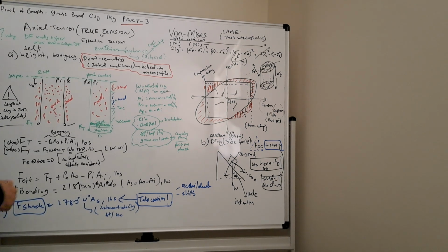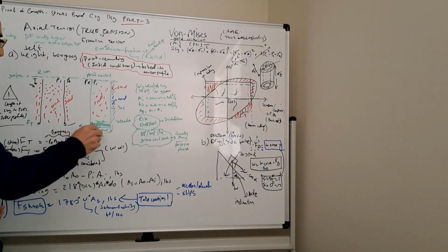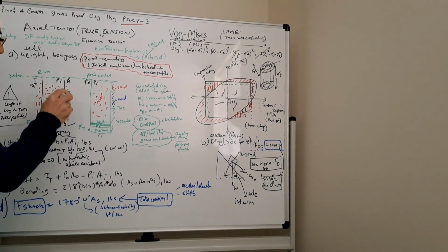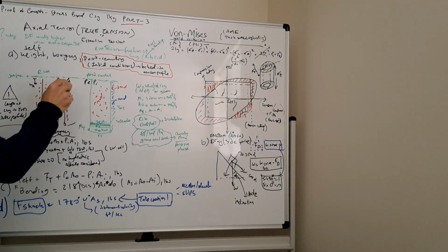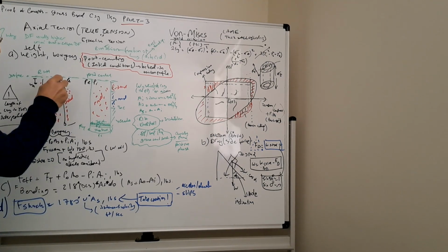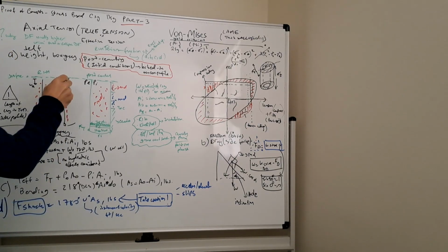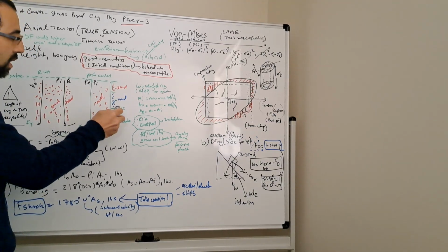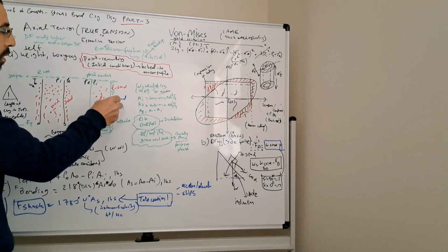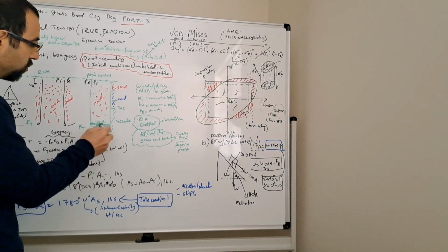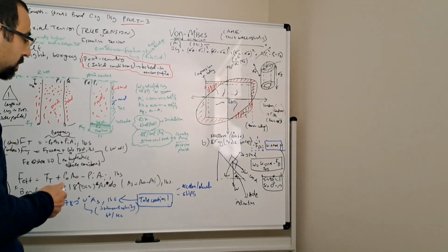So first, let's cover this. Let's look at these two schematics. I have drawn these two rough schematics here. On the left-hand side, basically the casing is running in hole, and you have mud inside and mud outside, so you have external pressure and internal pressure. Of course, at the bottom, you have the pressure impacting, and then on the right-hand side you have a cemented condition. I put a top of cement here, so there's cement here, probably a spacer there, and then mud above. And then you have the shoe track, and the top plug is basically landed over here.